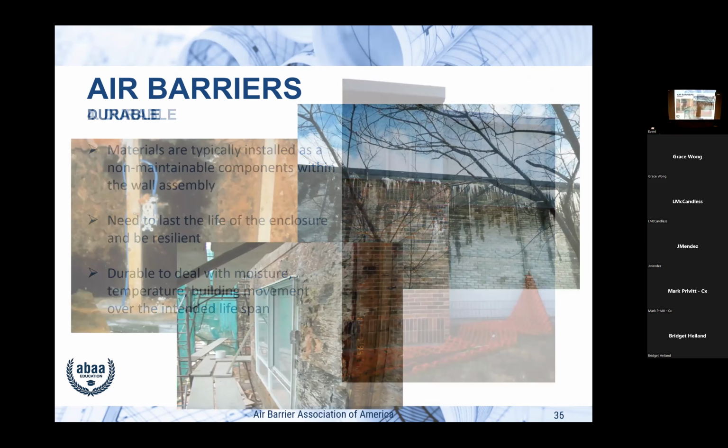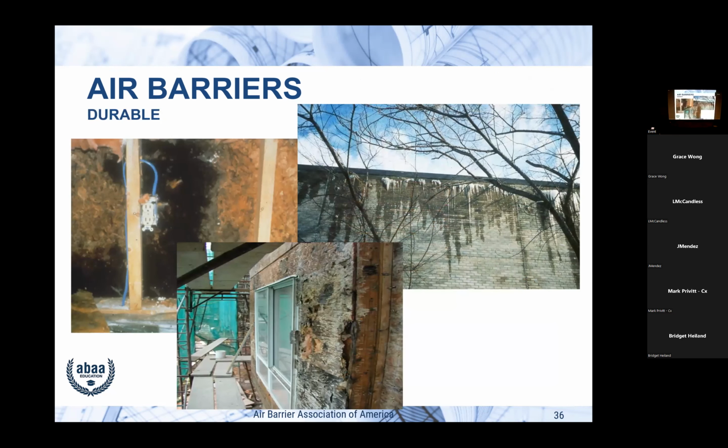And you see this all over the place. This is actually up in this area, the picture down here. If you remember, a lot of it was in Vancouver, BC. It's called the BC condo crisis, a $3 billion repair job. That's a condo in BC in those days. And most of it was liquid water coming from the outside, and there's a whole bunch of reasons why that happened. But it was also water vapor coming from the inside. If you ever want to read it, it's about 600 pages long, and it's called the Barrett Commission Report, and it blames everybody. And it's not wrong.